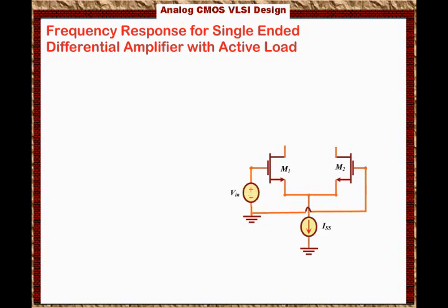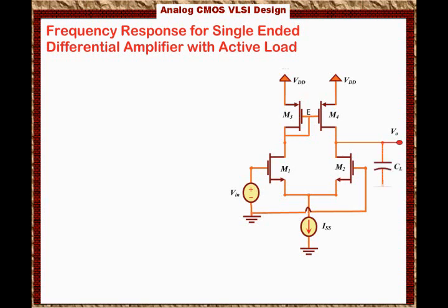and then the gates of M1 and M2 are connected to the differential input voltage, and then we have the loads, the diode connected active current source, where M3 is diode connected, and M4 is the mirror transistor of M3, and then we have the load capacitance at the output. Keep in mind that we assume CL is large in value and it is part of the load.